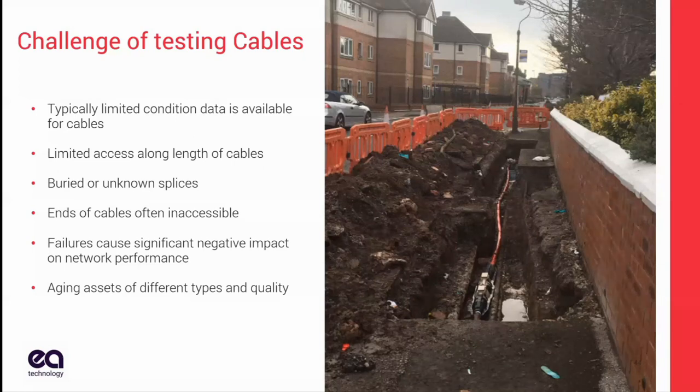I can't test it along its length. So one thing you can do is if you can get to the ends of the cables and you can run a test that covers the length of the cable from one end or from either end, that's going to make things a lot easier. Unfortunately, you can do that with partial discharge.